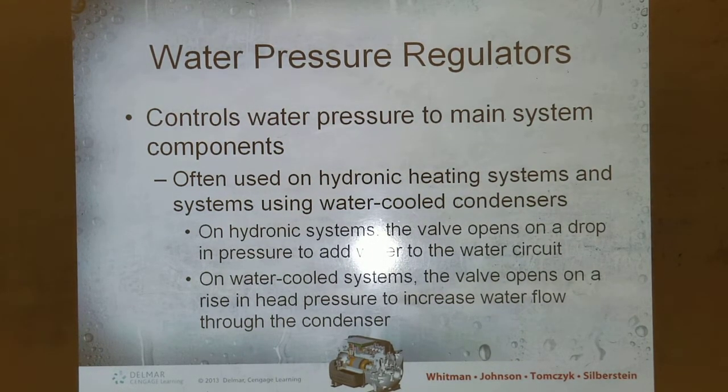Okay. You guys understand that? Kind of. It's just a water valve that modulates the water flow, especially through water-cooled condensers, that's what they're gonna use. The water-cooled condenser, as the pressure goes up in the system, it senses the pressure and opens the valve for more water to flow through. Okay.